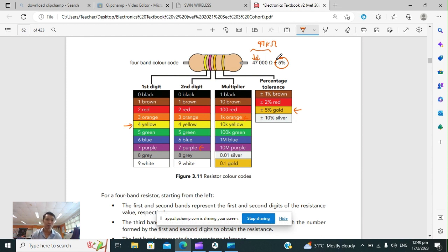Okay, there's usually going to be some sort of tolerance, simply because maybe the first cut by the saw is going to be a perfect 1 meter by 0.5, but after sawing 50 pieces of wood, it's going to be slightly blunter, the blades will be slightly thicker, and then instead of maybe 1 meter, there's going to be a 1 mm or 0.5 mm difference between the first cut and the 50th cut.